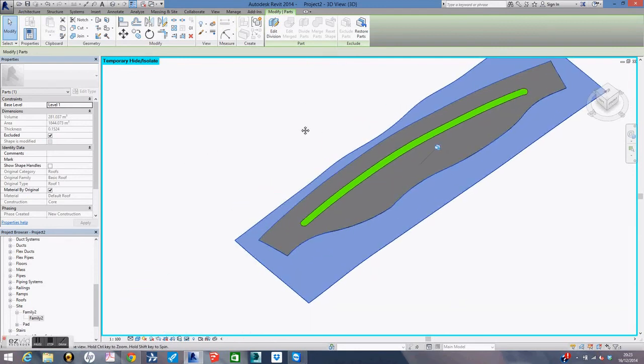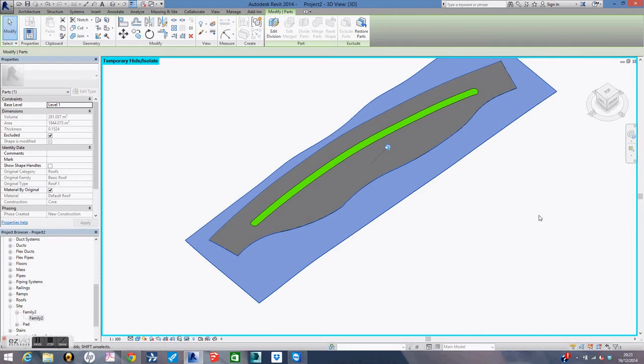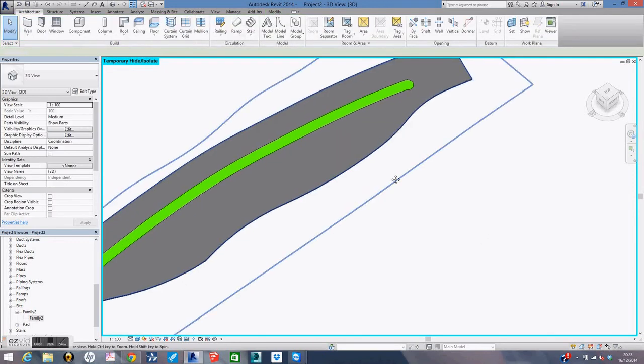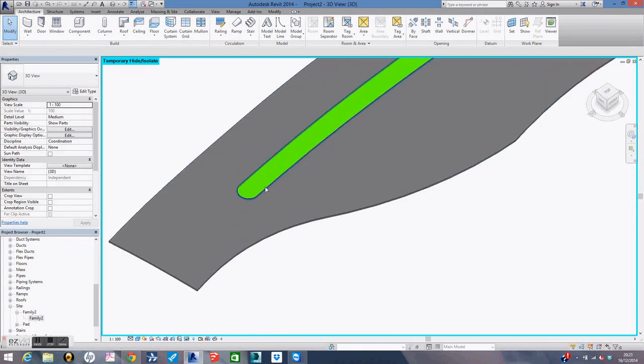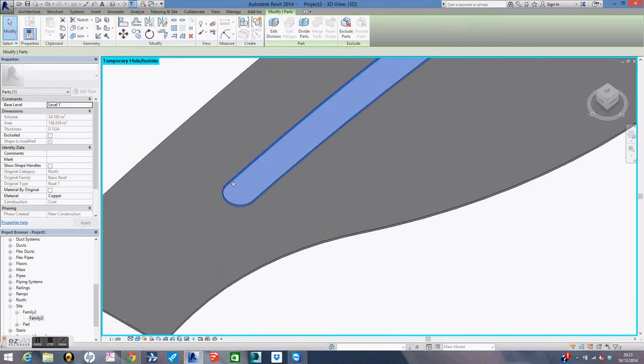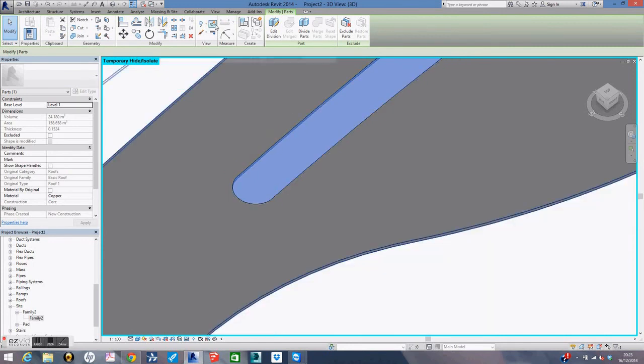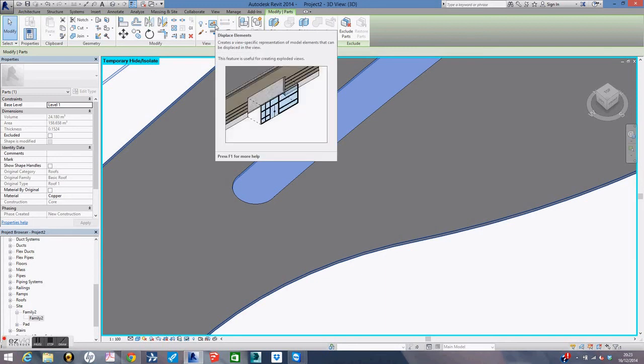What you'll find though is that you can move it in that direction. Yeah, and this is only for this particular view. This will not affect it in other views, but if this is for the purposes of really creating maybe context roads as opposed to design roads, then you might just want this for visualization purposes.